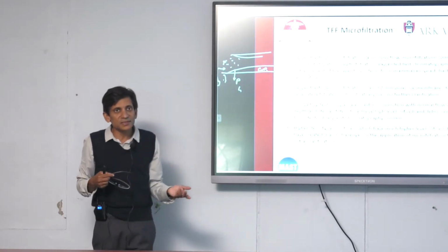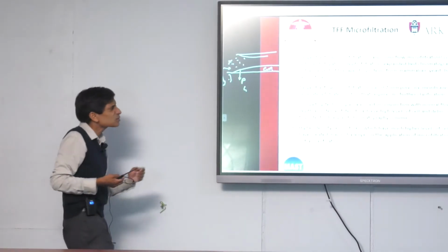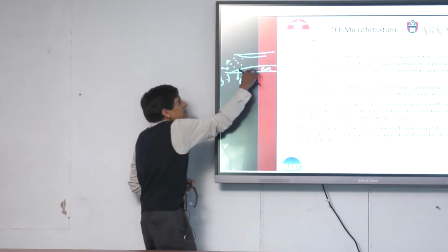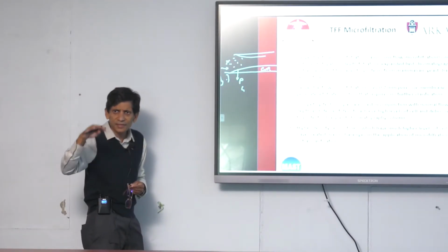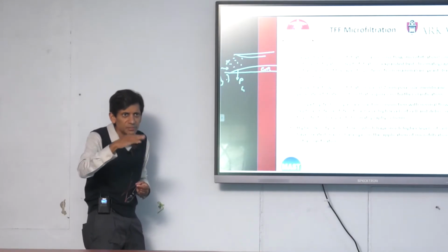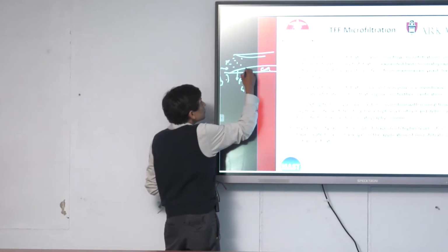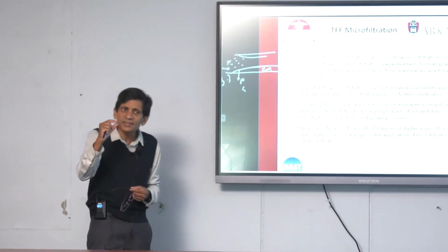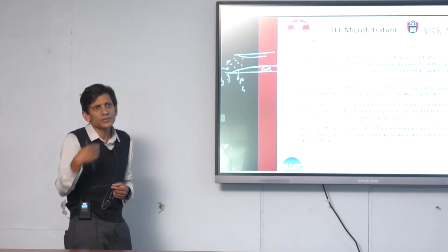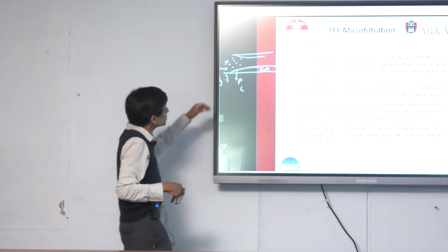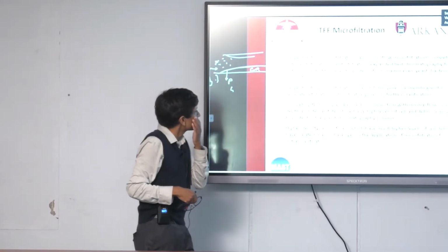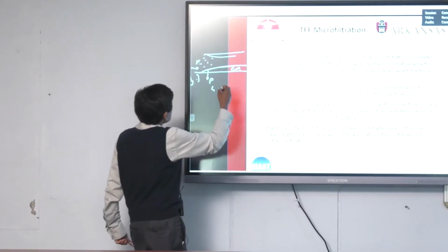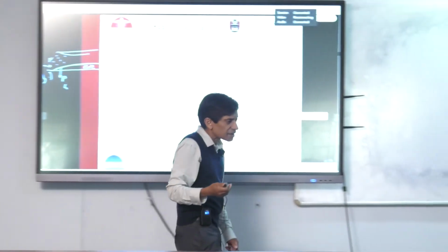However, in engineering terms, we find that difficult to work with. So we'd like to say there's a resistance due to this deposition, or not really deposition, reversible association of particles near the surface, right? They're not deposited. Depositing is a cake. It's a reversible association. But we say that if you draw a curve like this, say 90%, 95%, some number like this of the resistance is now within this, okay? So it gives us a way to try and quantify it. So you get this concentration polarization layer that forms, okay? And what happens then is that this actually is going to somehow limit the flux.